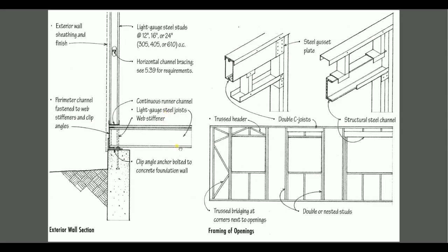Let's see another one here. So it's a foundation, right? Foundation is the same thing. We have the bolt. We have the C-channel stud here. So there's a continuous runner channel. We have the bolt here, bolted to the foundation wall here. So we have the C-channel stud here, and this is the top. This detail, this section is typical. It is the same as the wood construction.